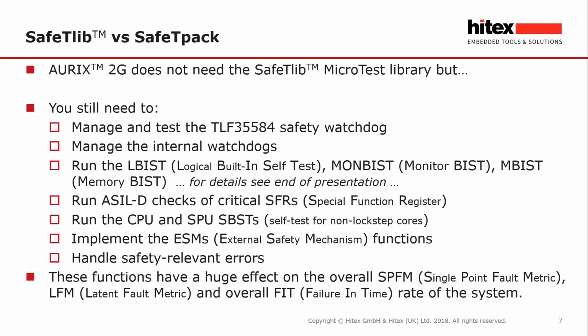These are the individual CPU watchdogs and the overall safety watchdog. You have to run the new LBIST, the logical built-in self-test, the MBIST and the MonBIST. These are provided in the silicon by Infineon. There are some things you have to be aware of when you use these, and the SafeTpack takes care of these issues.